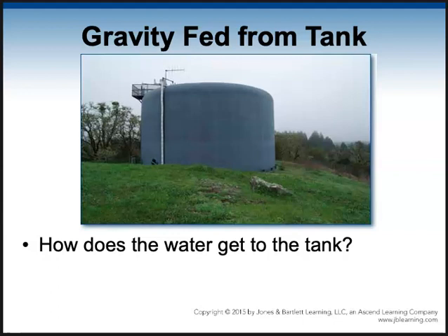A little float valve, and the float is styrofoam or something like that that floats on the water, and it's attached to a valve. When the water is getting used and the tank is getting drained, the float will go down to a certain point where that triggers the valve and turns on the pump to supply more water into the tank because it needs more water to continue to supply to the people.